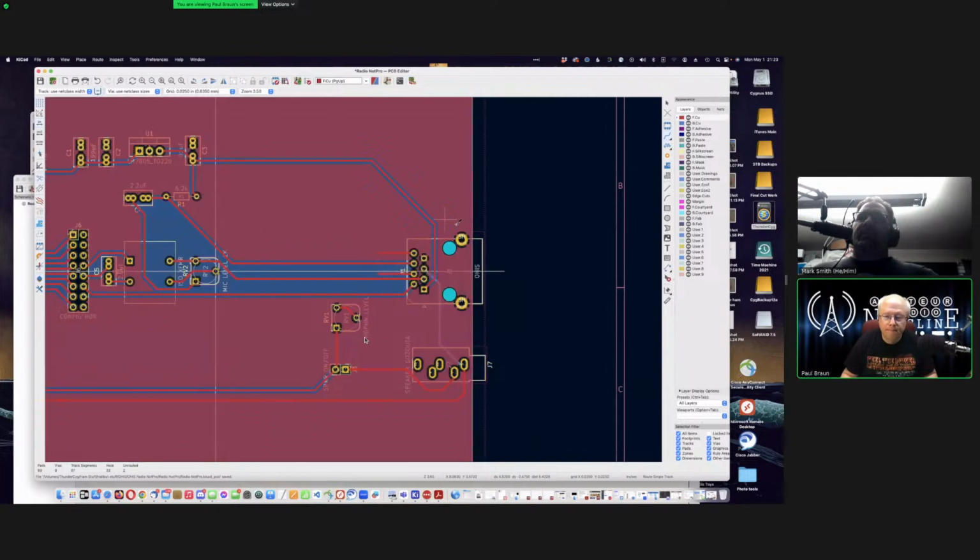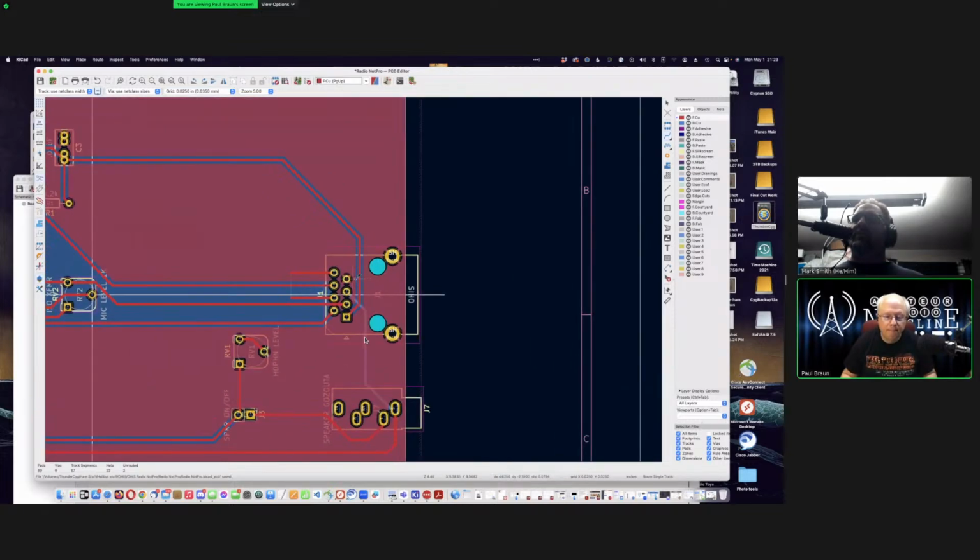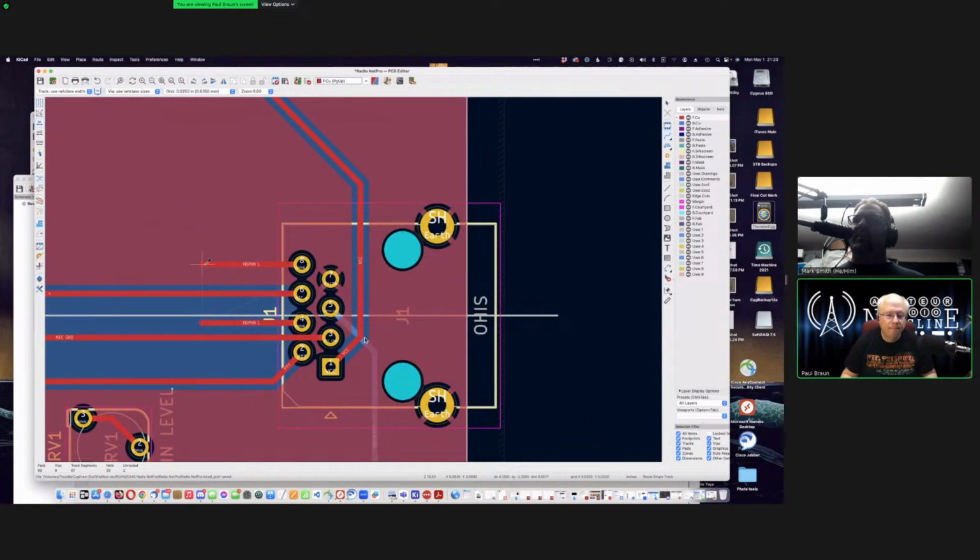Perfect. Okay. So now we are going to hover over those wire tips that you have hanging out there. Hit V, enter. Nope, I lied. Hit V again. So V is swapping things. Okay, go grab the via tool. V is what you do when you're in the middle of laying a trace. Click that and drag that and plop it over that tip. And then drop another one over that tip. There you go. Now go back to the blue layer and let's draw a trace.